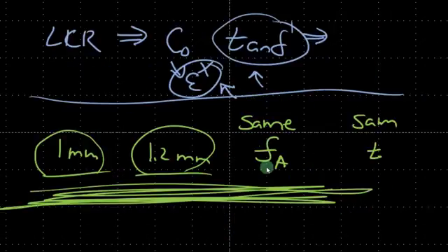So I said that you can use the LCR meter to measure the capacitance, which can give you the permittivity, and you can measure the dielectric loss. Due to coupling of properties in piezoelectric materials, determining this material property and this loss property can give you pretty much all the information you need to see if two materials from the same batch are the same. But actually what happened in this case was the thickness of the materials were different, therefore the resonance frequencies were different.